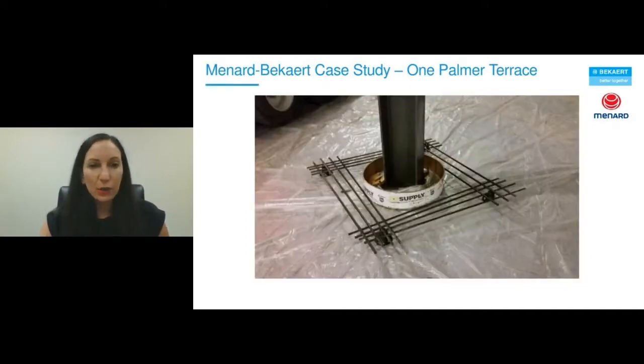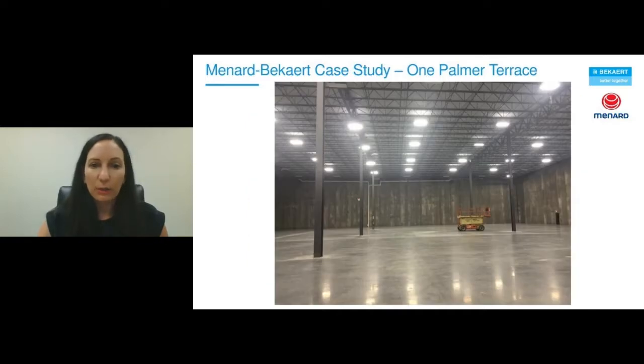We're still going to see good detailing practice in a project like this for sure. We want to see reinforcing around interior columns, re-entrant corners. In an interior column like this, we want to see a circular block out, compressible material, right? The same kinds of things that you would do ordinarily. And then you end up with a really nice joint-free solution. I believe there's only one joint in this 50,000 square foot project.